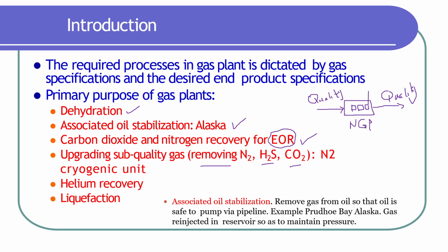Because for example, if you are dealing with a natural gas stream that has very low concentration of H2S and CO2, most specifically H2S, which is sometimes the case, and I think even in Oman there are some gas fields that have very low quantity of H2S, then this means that you don't need a treatment unit for the H2S. This means that you can simply produce your gas without passing the gas stream into what we call the H2S removal unit.